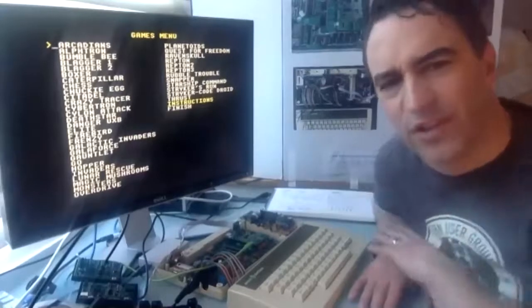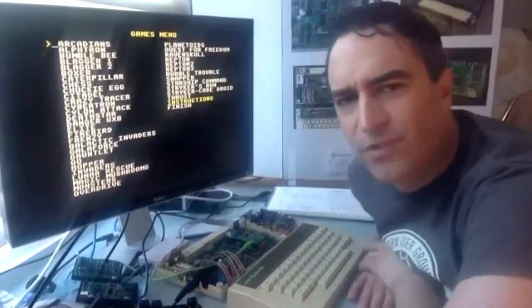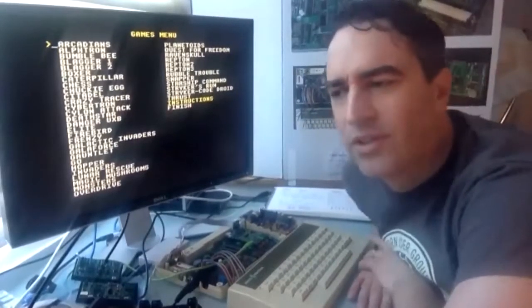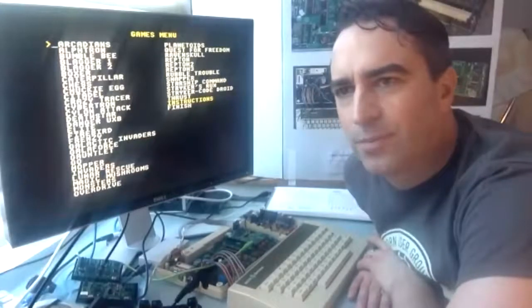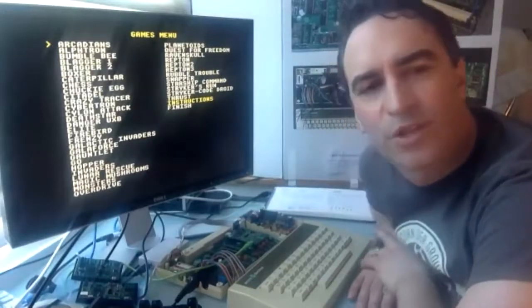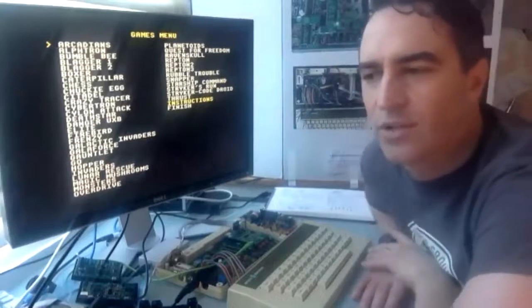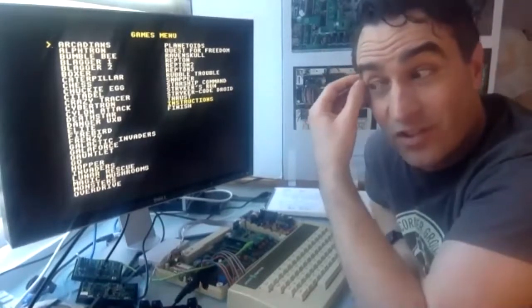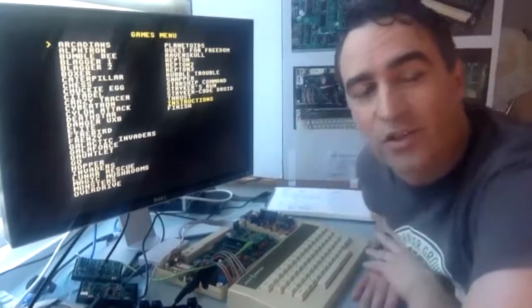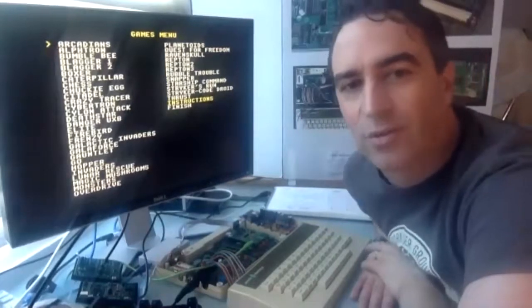There's all sorts of other things, like if you want to do ridiculous things like have several processors in it, but you want to make it kind of fast, you can do some sort of caching. The 6502 accesses the zero page and the stack page quite a lot. So if you put those in block RAM and everything else in SDRAM, it could run quite fast.